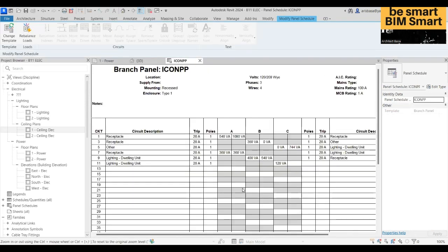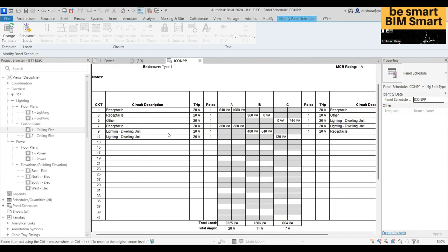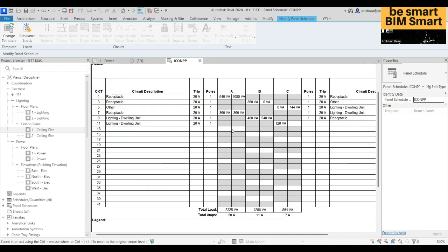There you go. See how many outlets do we have? Circuits for receptacle, right? And it is calculating how many amperes, volts we have. Now there's one more smart feature of Revit, which is to balance the load. Usually in electricity, they want similar loads almost, maybe to make sure that nothing is overloaded. So we have the tool here, which is rebalance loads.